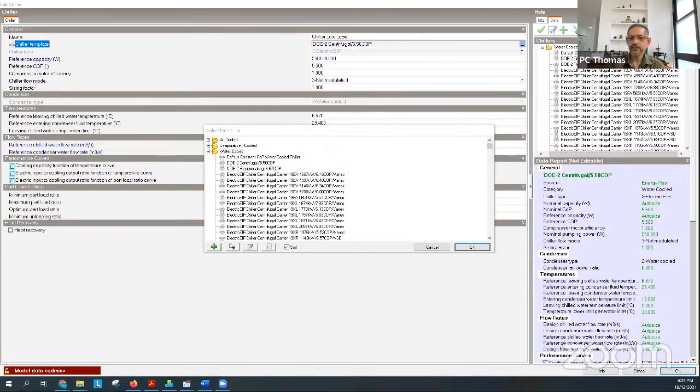Okay, because in a building you have a multiple chiller plant. The building is asking for different kinds of load levels at different times, and the IPLV by itself doesn't really make too much use. An experienced engineer will look at the IPLV, I don't know how many of them do it, but I do.